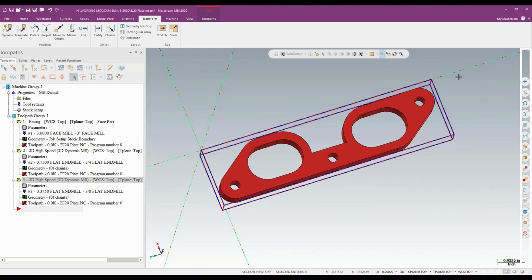So if I've got toolpaths that are proven out, and I think I'm probably going to use that one a lot, or I find myself using something similar, export it and just recycle it over and over again. If you're a lathe programmer, this really needs to be your standard operating procedure, because you're traditionally doing a facing, a rough, and a finish on a turning operation over and over again. They're usually not too different from each other because your parts tend to be somewhat similar. So why wouldn't I use the same three face, rough, and finish turning toolpaths over and over again? I'm just going to re-import them each time and reassign, rechain them.